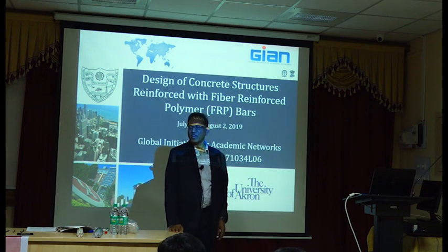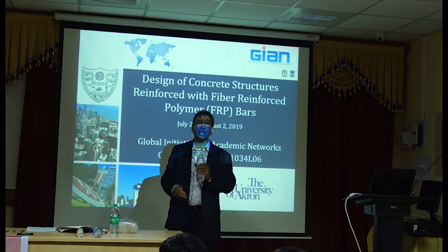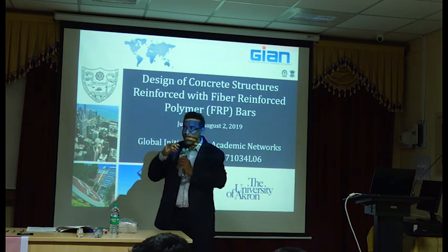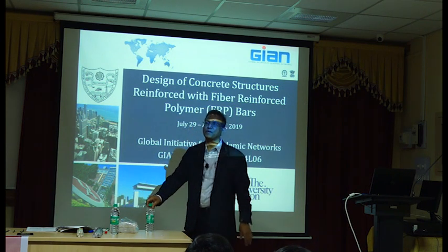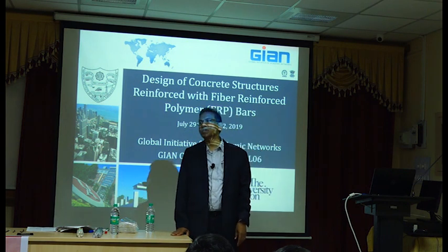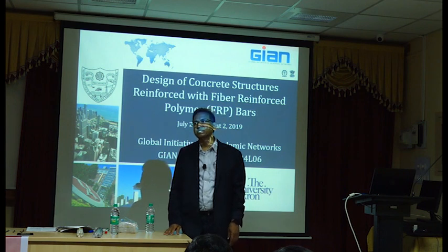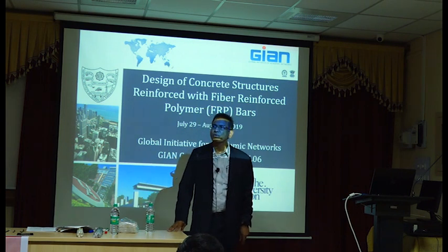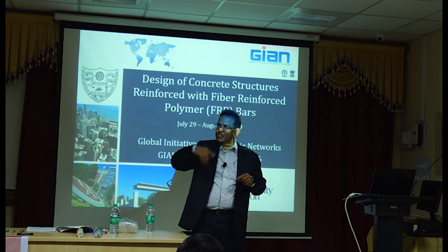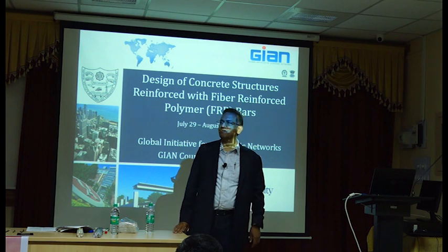Anything else? Do you have any questions? Should I move on to the next item? Can we use steel reinforcement with this? Yes, except with carbon fiber. You should always talk to the supplier. Sometimes they know there is a problem, so they put some kind of coatings. Because in bends we have issues with FRP, we can easily bend a steel bar instead. Yeah, mixed mode, absolutely. You can have stirrups in steel but main reinforcement in FRP. That works.